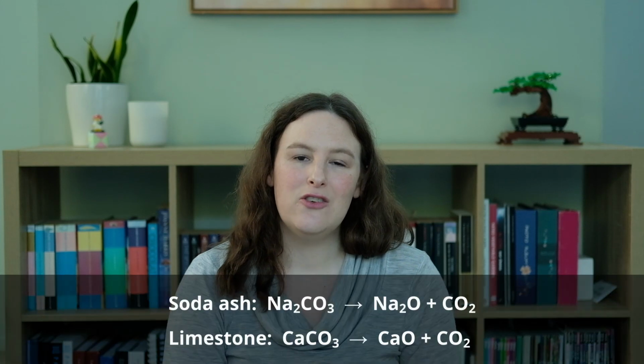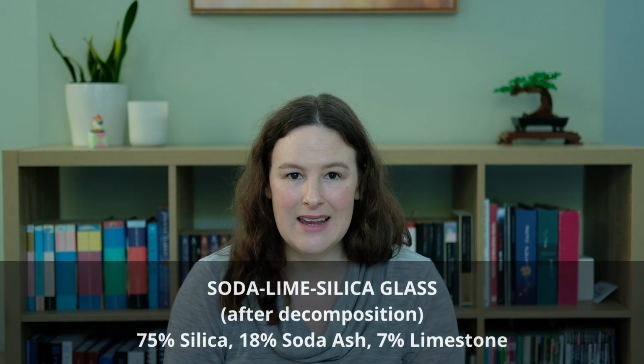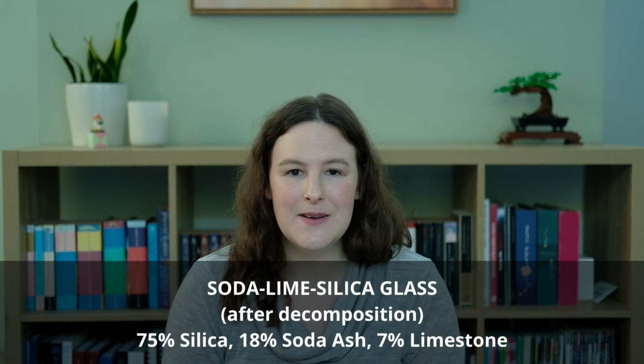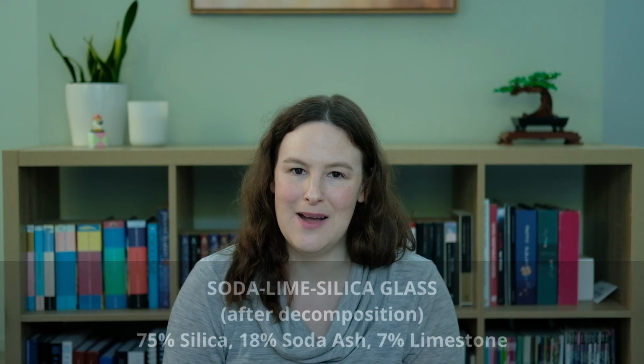Melting this mixture in a 1500 degrees Celsius furnace releases a significant amount of CO2 due to the thermal breakdown of soda ash and limestone into soda and lime. Following decomposition, the typical makeup of soda lime silica glass, ignoring any smaller additions, is 75% silica, 18% soda ash, and 7% lime. Once the molten glass has finished off-gassing and any impurities removed, it's cooled down to 1300 degrees Celsius, increasing the viscosity to a honey-like consistency, which will strengthen the final product.